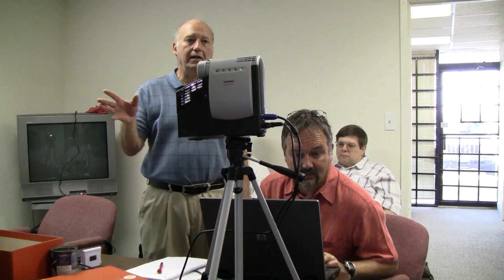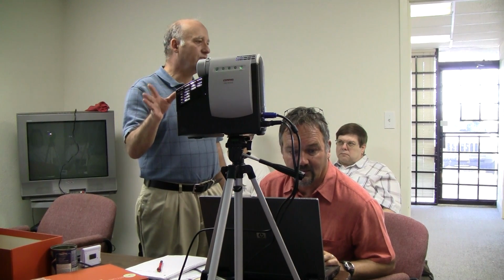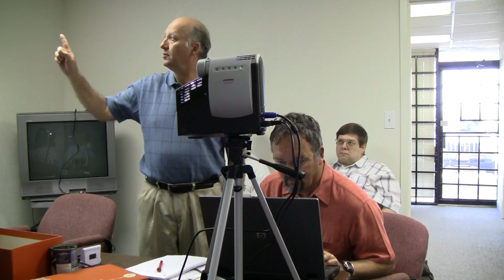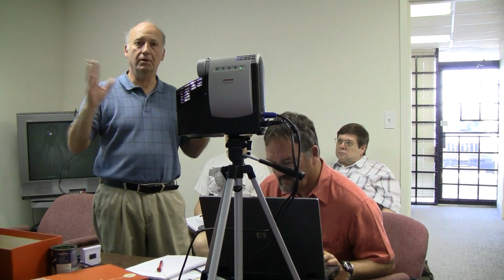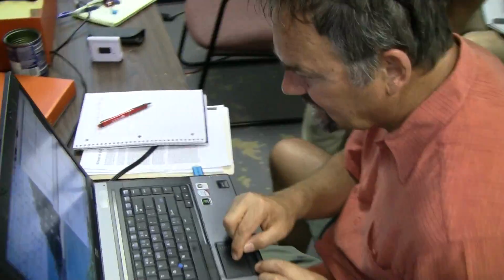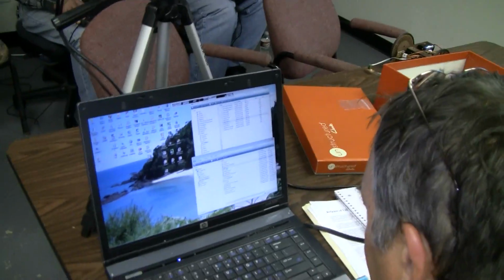If you've got KiCAD open, then you just have to open this file and then click on that last icon, and it will open up the auto router for you. Can you bring it up to the front too when you find it? Yeah. It's probably under tutorial.